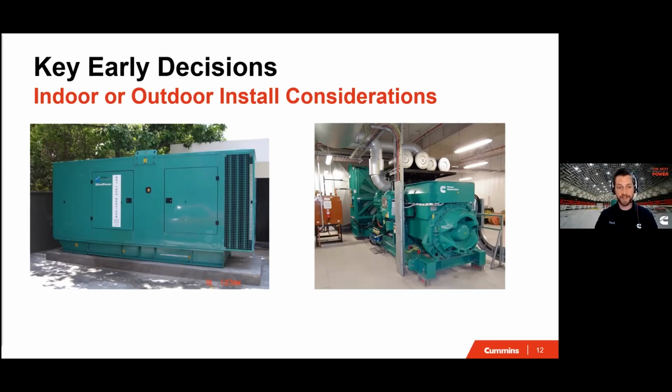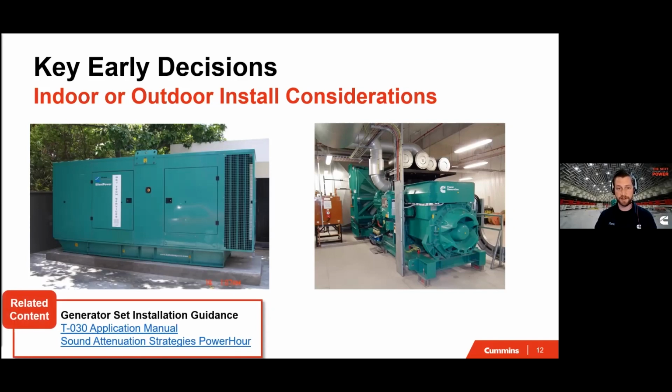So looking at the indoor installation on the right, this approach can be a great option, but may come with the added complications of keeping the generator set cool with adequate airflow or keeping noise and vibrations from transmitting within the building with proper isolation. So of course, I said there are many considerations at play here, but I cannot go into each and every one of them. I recommend for further reading our T030 application manual, our complete and unbiased approach to best practices in mechanical and electrical design in and around generator sets and power systems, both indoor and outdoor.